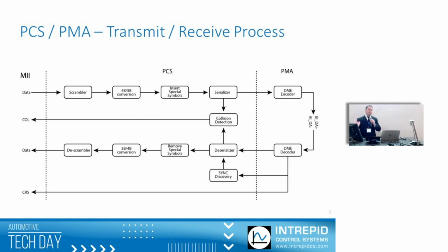By reusing these old concepts, the carrier sense and the collision detect, these go back to the 70s, it enables the PHY to be lower cost, because the only other way to achieve 10BASE-T1S on a multi-drop network where only one node can transmit, that means some nodes will have to wait. And if some nodes have to wait, you'd have to buffer the data, right? So instead of buffering the data in the PHY, you could specify that the PHY has to have a certain amount of buffer to handle this possibility of collision, but then that increases the cost of the PHY. Then you have to have memory in the PHY, and it adds a lot more complexity. And one of the main intents of this is to be a very low cost, very simple type of network, as simple as possible. Essentially, what 10BASE-T1S has done is push the logic for the case where the network is busy, like a collision detect in the old world.